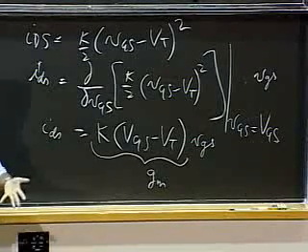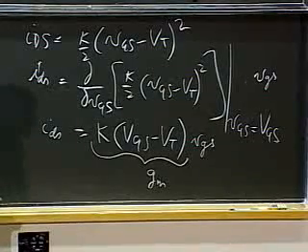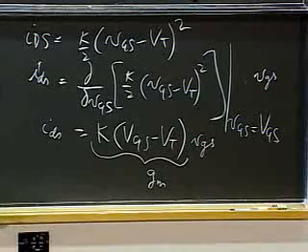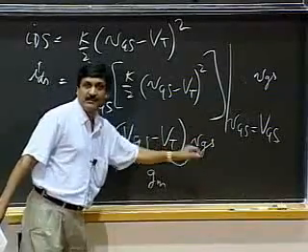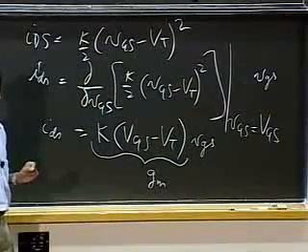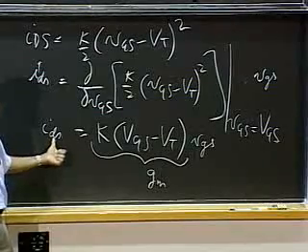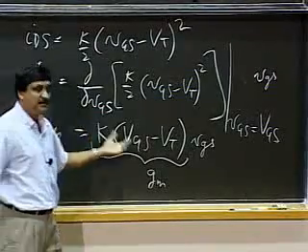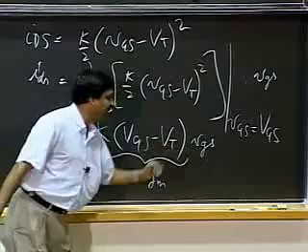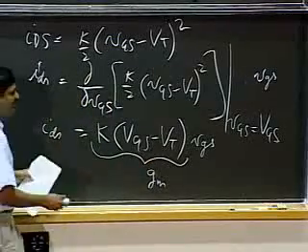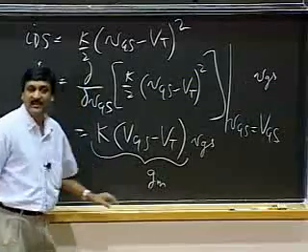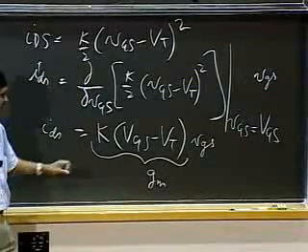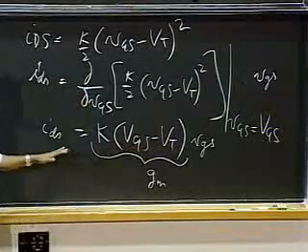Notice that the resulting small signal model is also a dependent current source. It's a voltage-controlled dependent current source. So the output is a current, and it's a dependent current source, and it depends on the input voltage. The good news is that this expression here, GM, is a constant related to the bias point values.